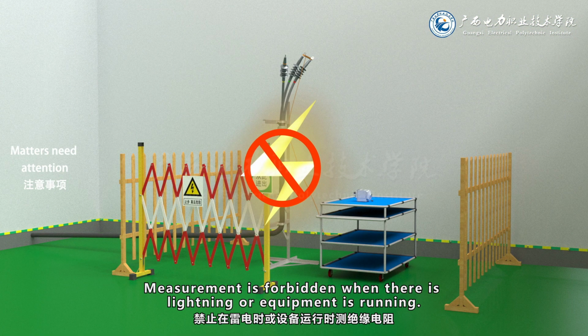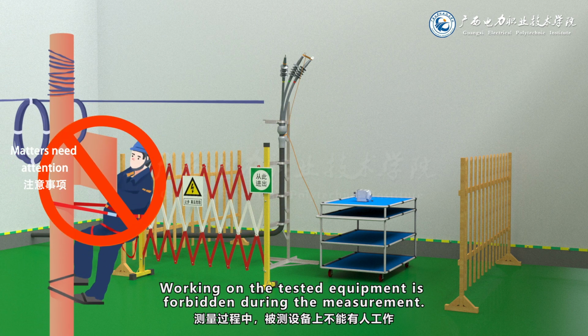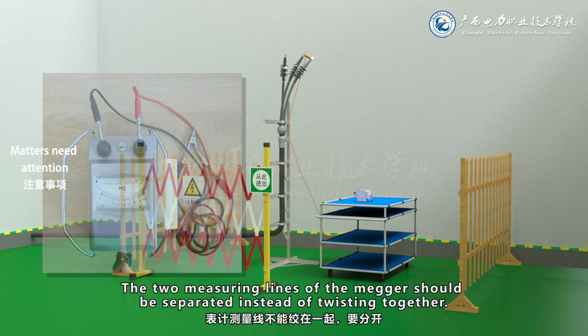Measurement is forbidden when there is lightning or equipment is running. The equipment can only be measured when it is uncharged or unenergized. Working on the tested equipment is forbidden during the measurement. The two measuring lines of the Megger should be separated instead of twisting together.